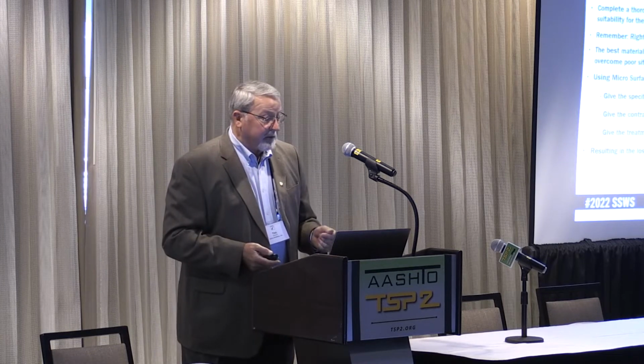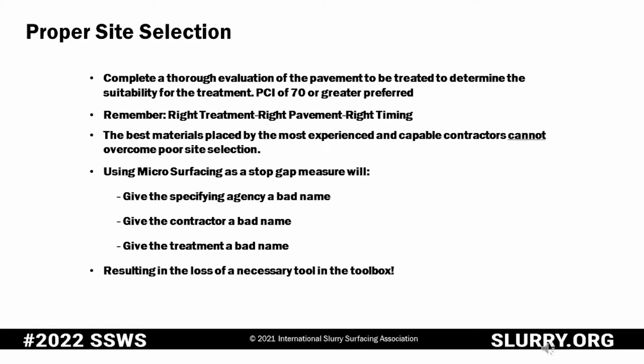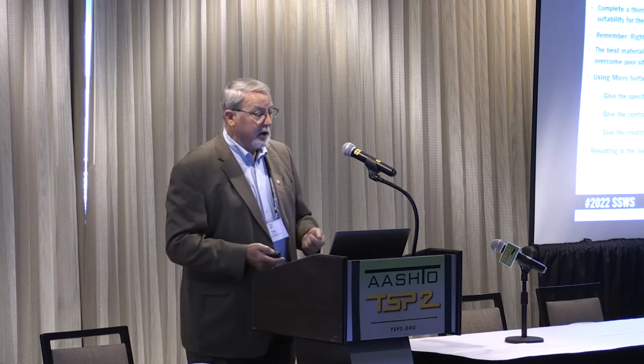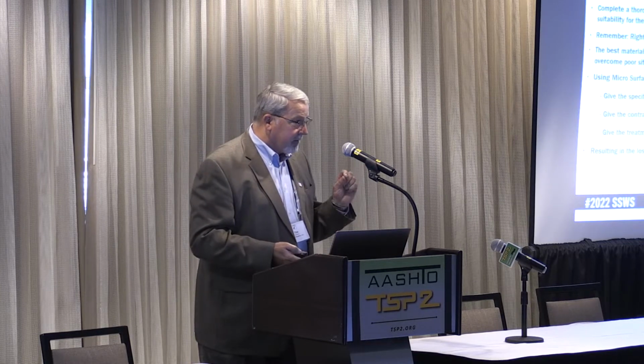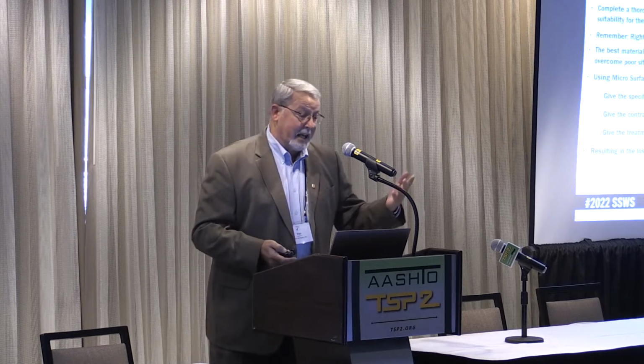You don't want to use microsurfacing or any thin structural non-surface preservation treatment as a stopgap measure. Ultimately, that will result in the specifying agency getting a bad name. It will give the material a bad name, and it will give the application contractor a bad name as well. And the end result would be one less arrow in the quiver as far as preservation treatments to take care of the business at hand. So be very careful when you do that. Do your due diligence when it comes to proper site selection. That is first and foremost when it comes to good quality micro or any kind of a project for that matter.